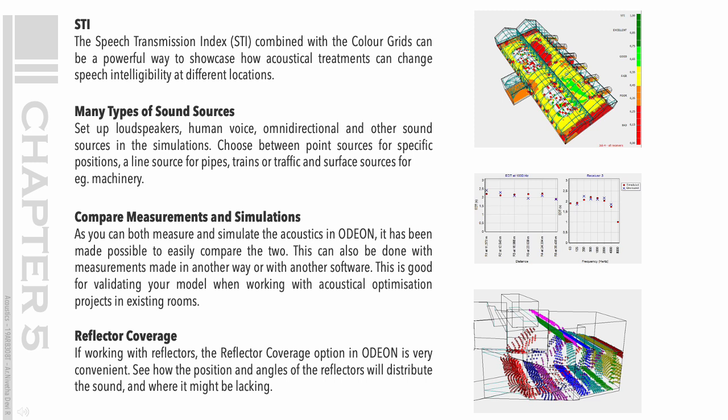As you can both measure and simulate the acoustics in Odeon, it has been made possible to easily compare the two. This can also be done with measurements made in another way or with another software. This is good for validating your model when working with acoustical optimization projects in existing rooms. Reflector coverage. If working with reflectors, the reflector coverage option in Odeon is very convenient. See how the position and angles of the reflectors will distribute the sound.